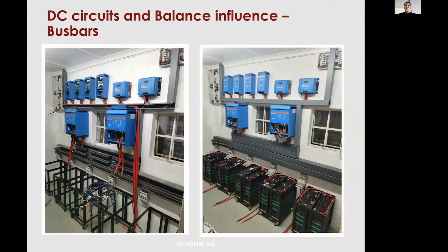So if you see in the picture next to you, he put every battery set, there's the 5 battery sets with the BMS in between, and these are the cables here to connect them to his breaker. Very important point, those breakers, he's got one breaker per battery set, and each of those breakers are 120 amp fused, and he has one on each part of his 50 mil cabling here.